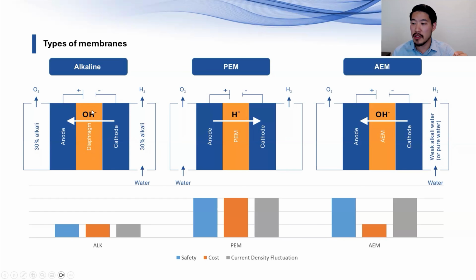With this being an older technology, it's usually a diaphragm, that type of membrane. So I rated it lower on safety because, with such a higher pore size, hydrogen can potentially cross through, which is something that we don't want. When H2 and O2 combine together in midair, that can cause an explosion. And so we don't want that to happen, which is why we say that this is sort of old technology that should be pushed away.